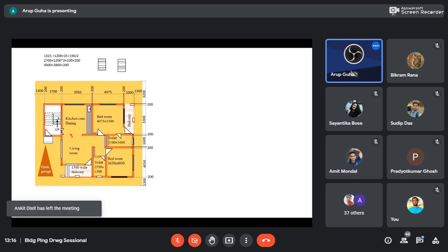If this protrusion is too much, you'll have to walk like this. So a double door is helpful here. But external walls, doors should not be double leaf, because that is weaker actually. Internally double leaf is better. It actually reduces hindrances. But this is hinged over here, locked over here.